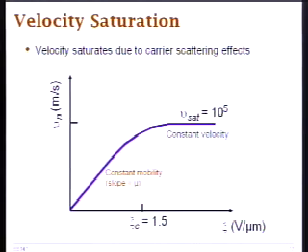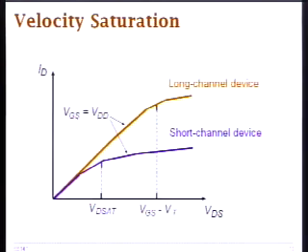And for the NMOS, it's about 1 to 5 volts per micron. And we did some quick calculations last time when you have, for example, a quarter micron long channel, and EC is equal to 2 volts per micron. Then you have your velocity saturation occur at VDS of only 0.5 volts. So your transistor automatically enters velocity saturation.